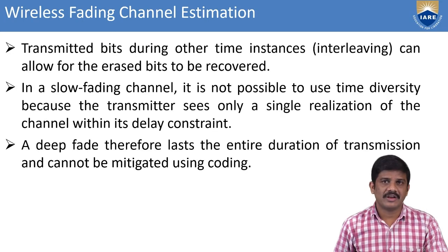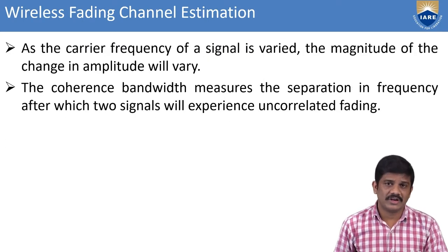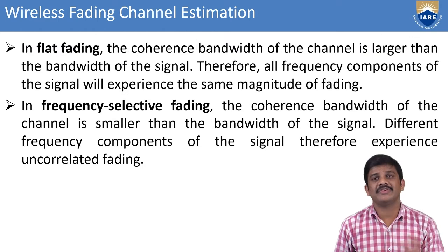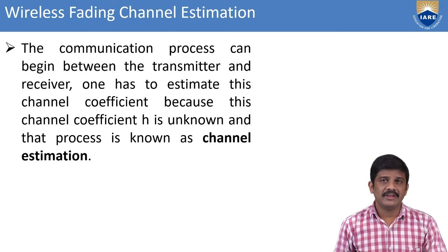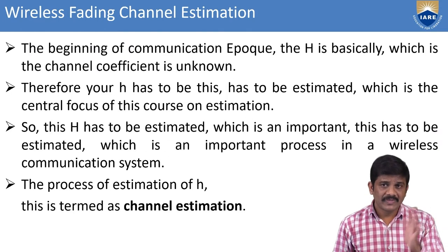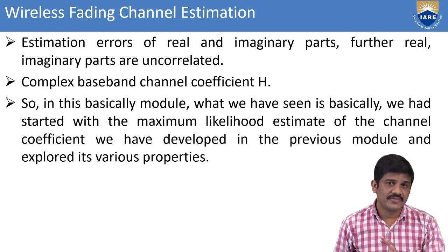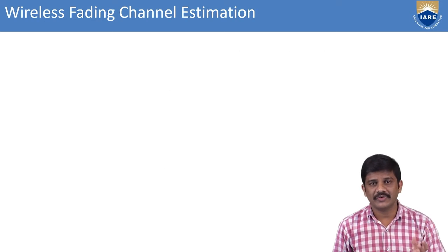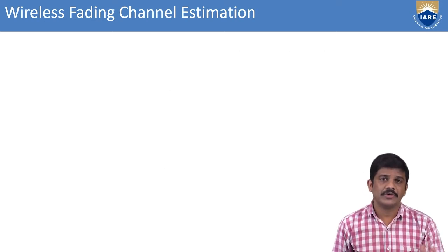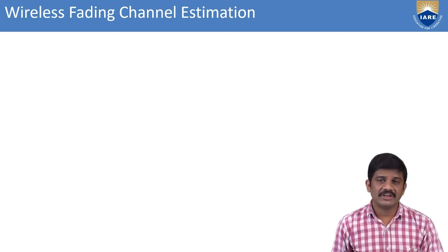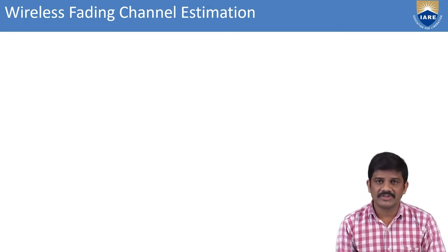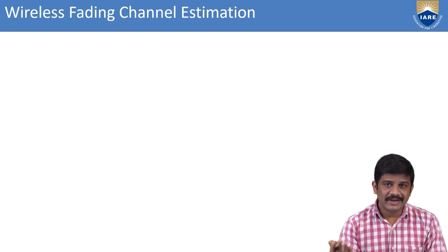This is in the correcting phase, and we are considering the Doppler shift also, which we took in the previous sessions. Coming to channel estimation, what will happen? We take the channel coefficient, the received pilot symbols and the transmitted pilot symbols. In between those, we do the channel estimation. For that we took the likelihood function in the previous class, but now we are finding the maximum likelihood function. For that, I can recall this.